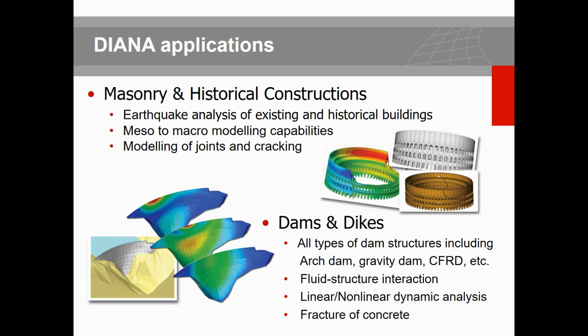For dams and dikes, Dana has a unique solution in order to cover all aspects associated to various types of dams. And this comes because of the soil structure interaction, coverage of material property for the foundation and the soil and rock, and modeling the faults, and also the superstructure and the main body of the dam, spillways, the gates, everything. You can model them and you can incorporate them with the unique features and analysis associated to the fluid structure interaction, time history analysis, linear or nonlinear, and also induced damage or failure or hydrodynamic pressure that are acting on the structure.